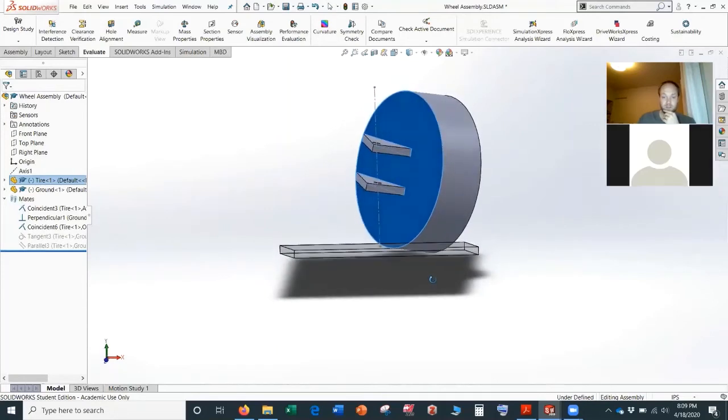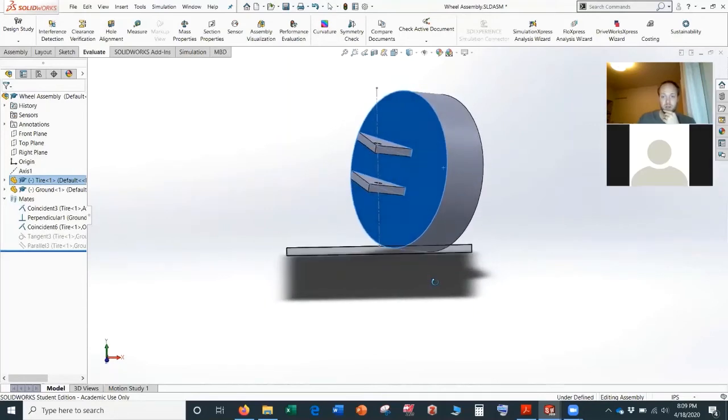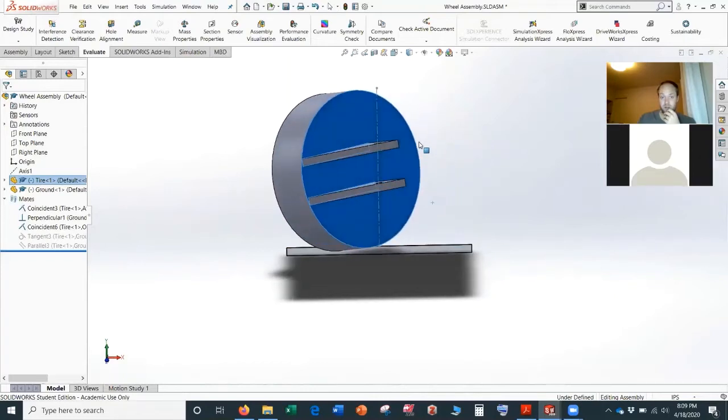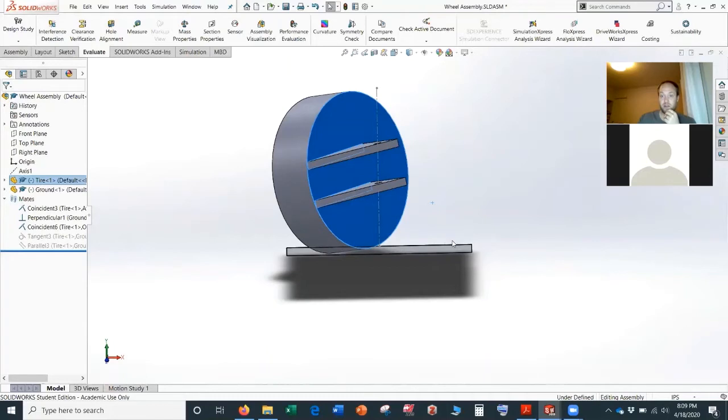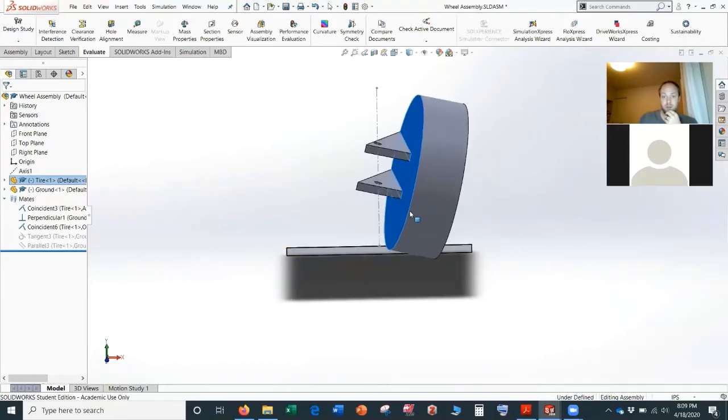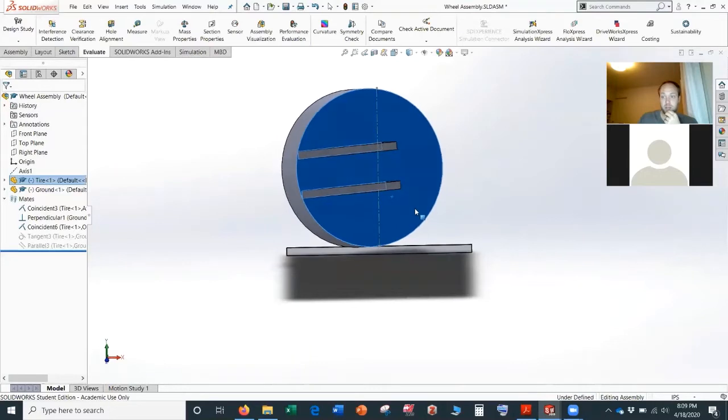right-hand turn. You see now with the scrub radius, it's much more pronounced how much the tire is going down into the ground basically. But as you turn in both directions, that direction, or you turn it back, it's going down into the ground, right? So the scrub radius and kingpin inclination definitely interact together quite a bit to do this. So it's not just one or just the other. You have both, and that's why we typically recommend 5 to 10 degrees of kingpin inclination, and an inch or two